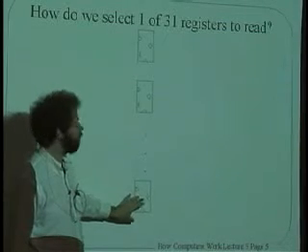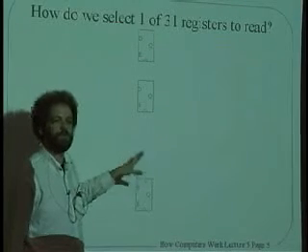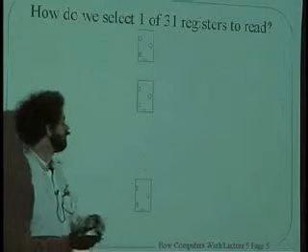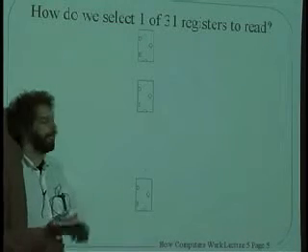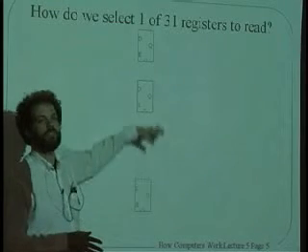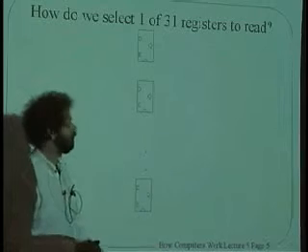And if you remember, R30 and R29 and R28 were special ones that we're going to use for special purposes, like the stack pointer and the linkage pointer and stuff like that, basic frame pointer and the exception pointer. That doesn't matter. We still have 31 registers. And then this last funny one, which is all 0 all the time.